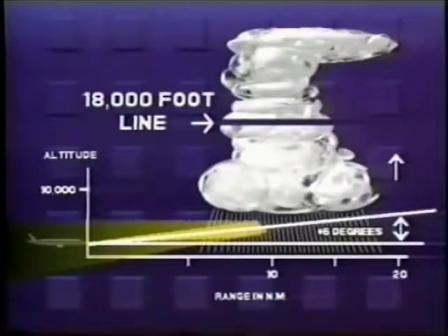Evaluating weather should be an ongoing process until the landing is completed. Keep the radar display in your view and be prepared to initiate a go-around if threatening weather appears on the scope.